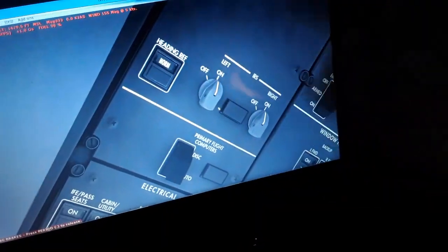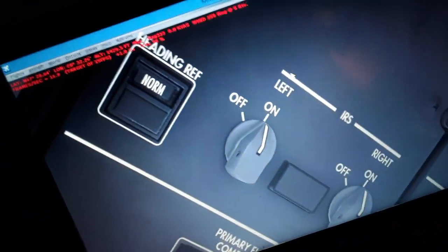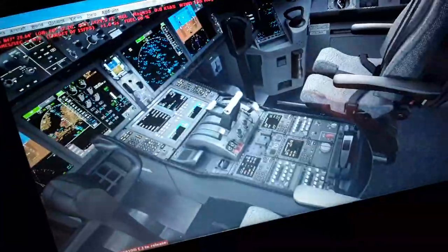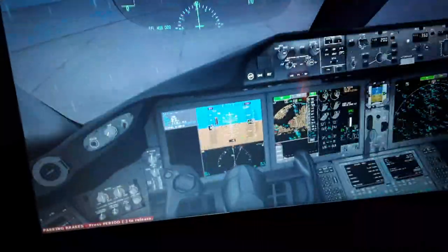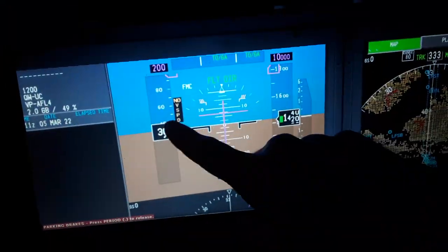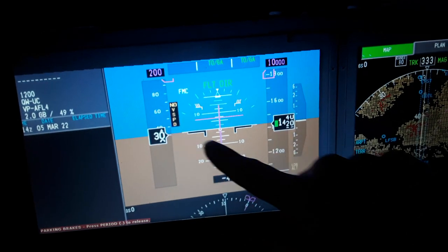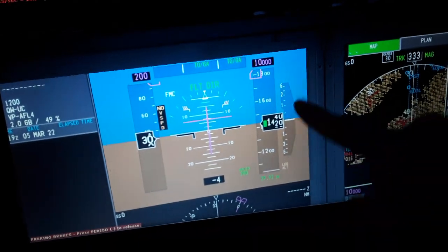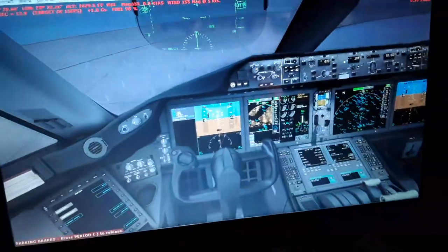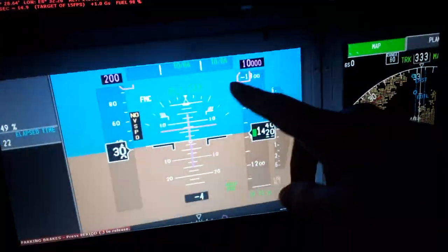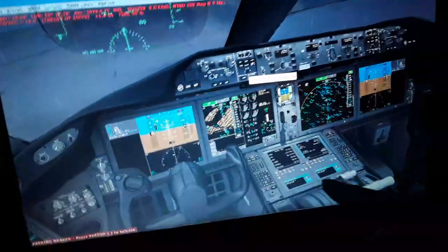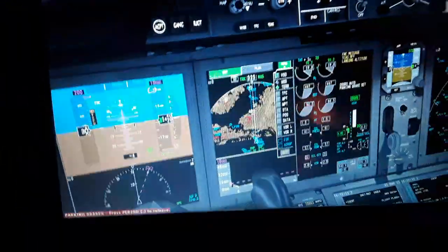We have also the air data computer over here. You can see heading reference alignment, inertial reference alignment. We can do it flight control computers, flight control services. So the air data computer displays the airspeed, the pitot dynamic and the pitot static for the barometric altitude and the vertical rate of climb descent, with the difference of the air pressures calculated, the angle of attack of the aircraft as it flies, the pitch attitude, the GPS position, the magnetic north pole, the graphic north pole.